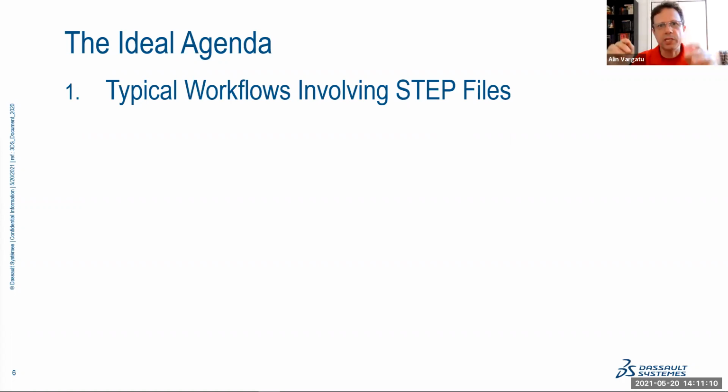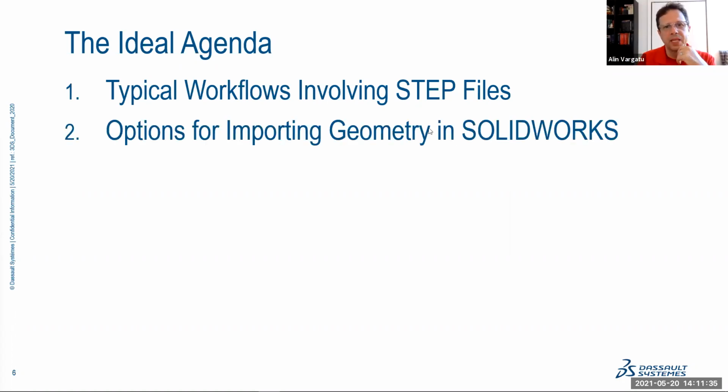And then they say, hey, we changed something, so let me send you another STEP file. What are you going to do then? Is there a quick way to update your geometry and also see what's different between the old one and the new one? And even more, make sure that any mates that you apply to the old STEP file will still work with the new STEP file. So very, very interesting. We're going to analyze how you're going to use the STEP file. Then we will cover ways to import. And when I say STEP file, I'm talking about any type of imported geometry. Okay, I'm going to use the word STEP instead of imported geometry.